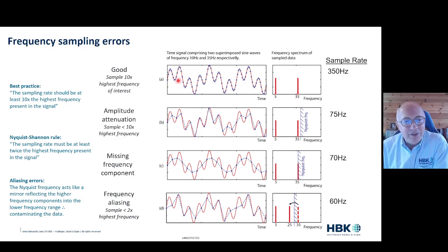What that means in fatigue terms is I've got quite a few points so that I can capture the peaks and the valleys. Because remember, fatigue is exponentially proportional to the amplitude. So it's important we've got enough points to represent those peaks and valleys when we do our rainflow cycle counting. So a factor of 10 is good.